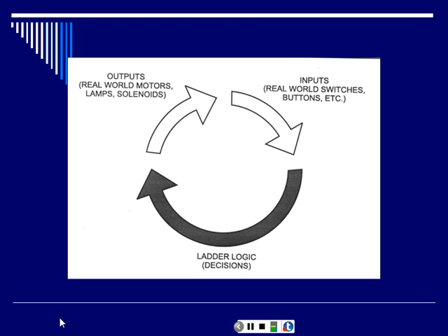All right, then after it does the decision making, it decides what goes through, and then it will turn on or turn off the motors. They're not actually wired together. So when we do motor controls, we take a wire from the hot. We go into the stop.